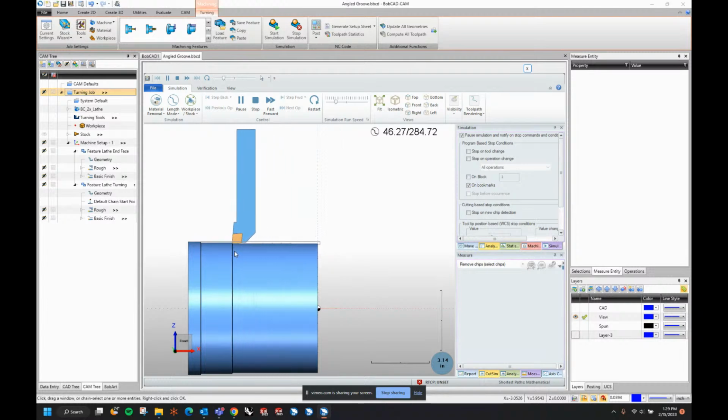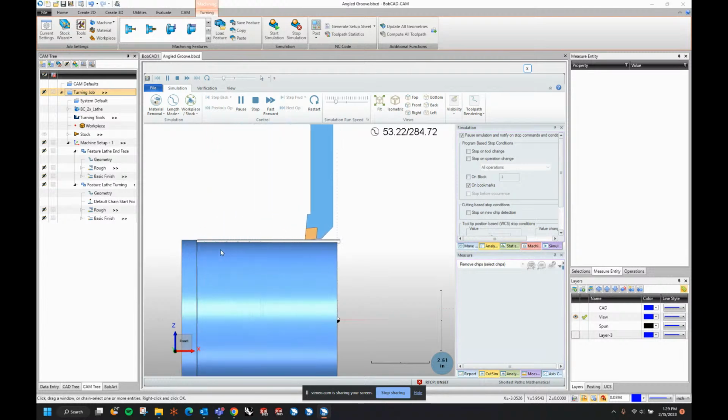So you can see it retracting along that. I might need to increase that retract because that might not actually break the chip. But those are a couple of the settings that I usually do right away when I load simulation, just so I don't ever have to touch them again. I often forget about them by the time we get to a new version.